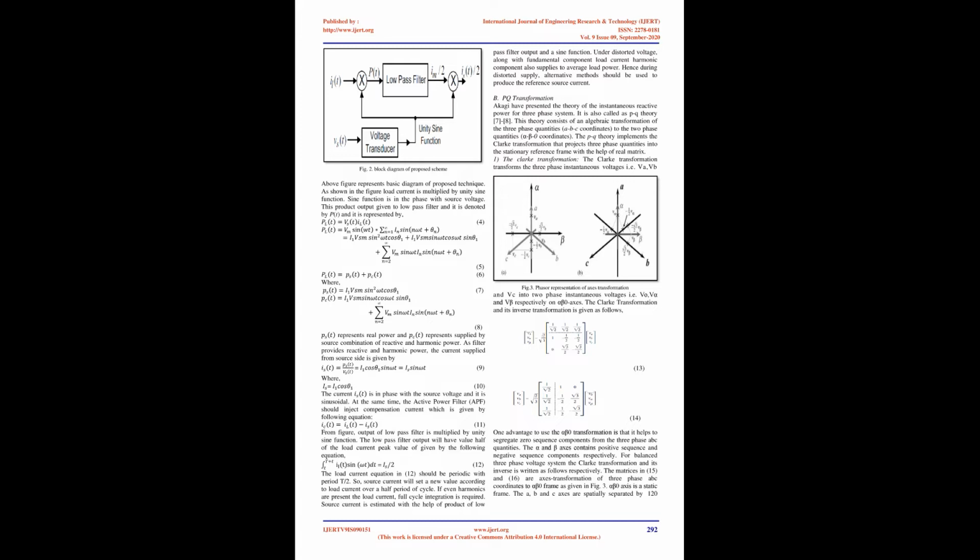The use of the above-mentioned electronic devices is responsible for harmonic disturbances as well as reactive power disturbances. Harmonics and reactive power are the main reason for various problems including transformer overheating, feeder voltage distortion, excess neutral current, malfunction of sensitive equipment, poor power factor and damage to electronic devices too.